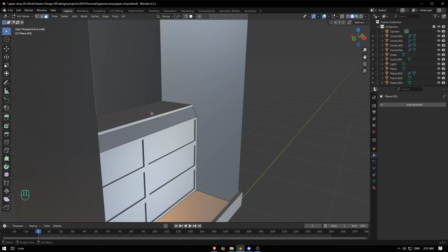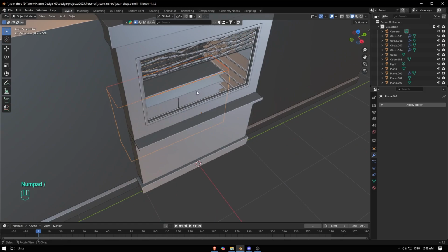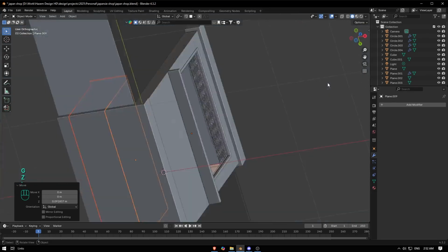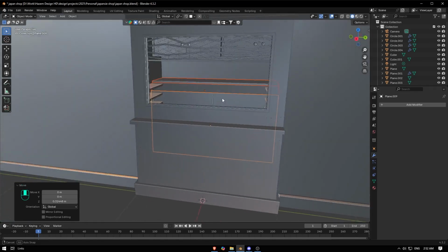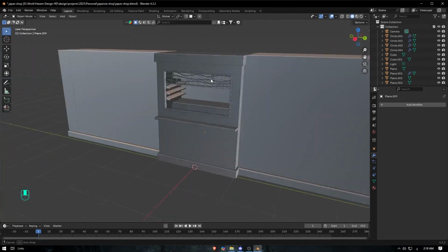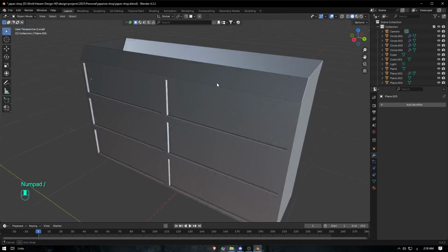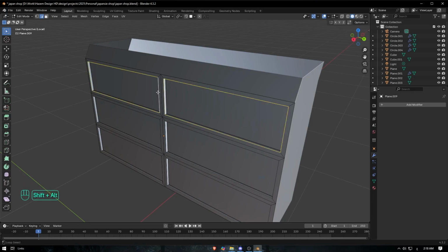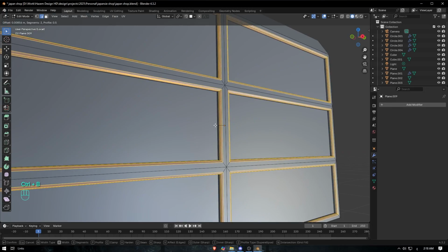This is going to be metal, and maybe here we have some product or that stuff. So let's go back, and I need this one to be boosted, so I can see it from here, like this. Or maybe this, I don't know. I'll try to add more details and extra stuff here. For the details, select these frames here and select the outside edges, like this. And go with Ctrl B for the bevel, and maybe 2 is good.